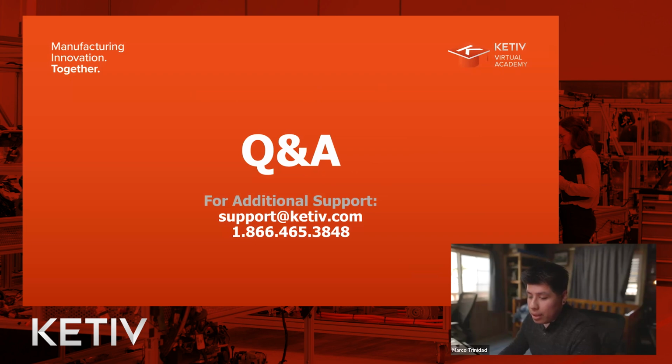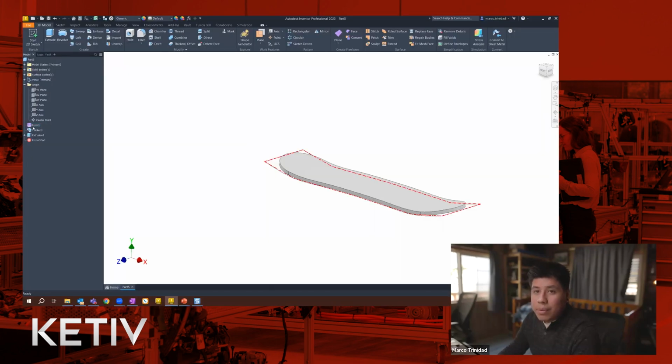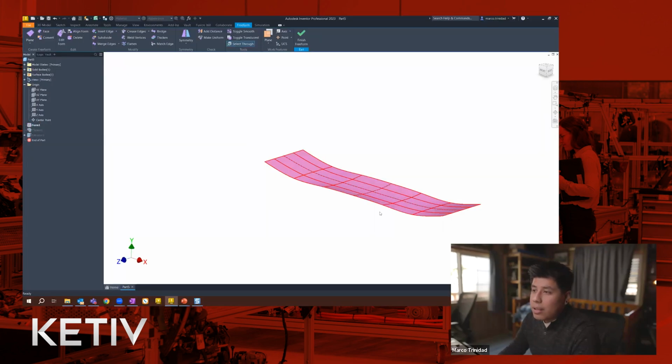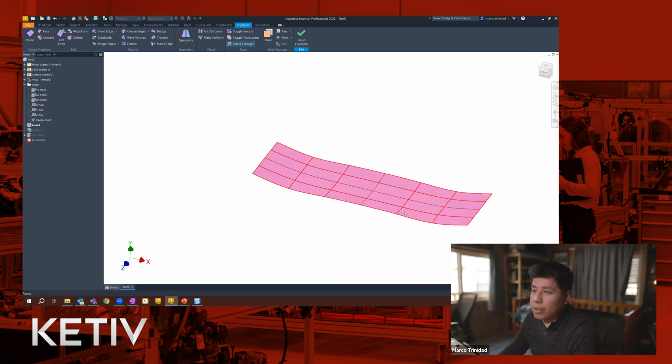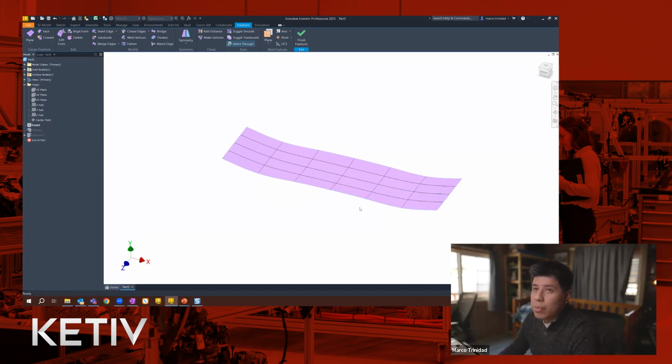How do you estimate the right amount of surfaces when creating a new freeform? So inside of freeform, let's say I realize I want more nodes in here. There are actually tools inside of here that allow me to divide it. If I realize that I want to add symmetry in different places, there's actually a tool for that up here.